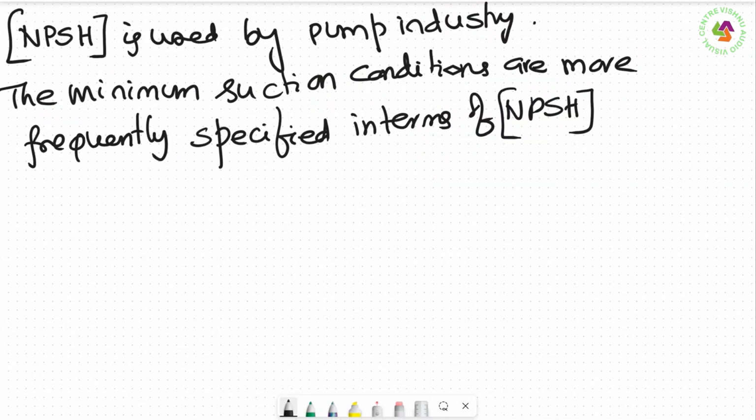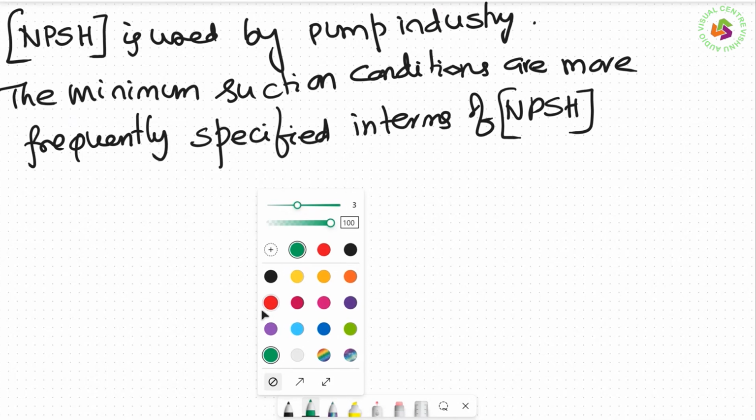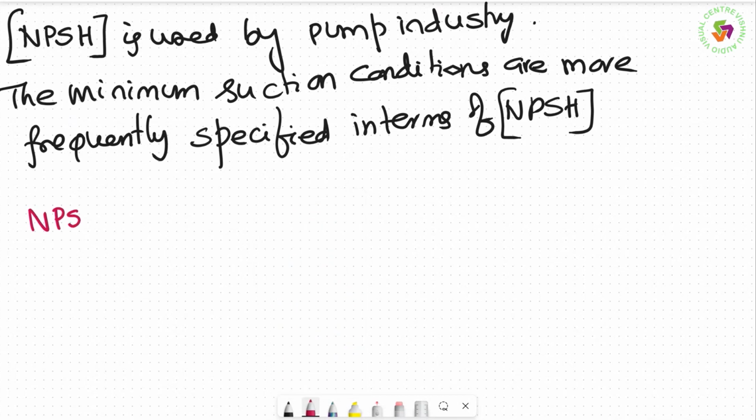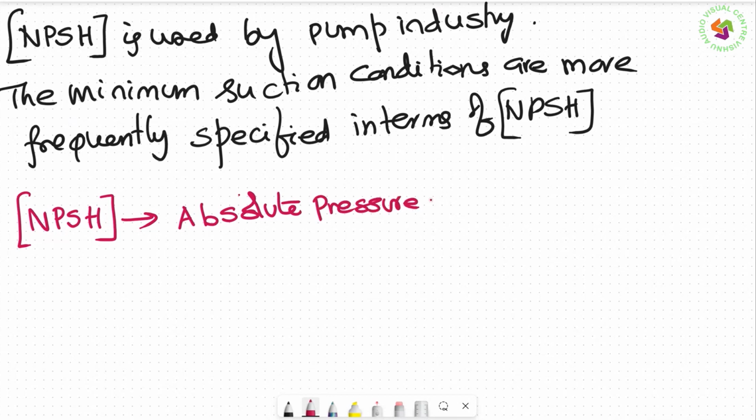Let us define what NPSH is. It is defined as the absolute pressure head at the inlet, because we know that at the center of the pump it is only the vacuum pressure.